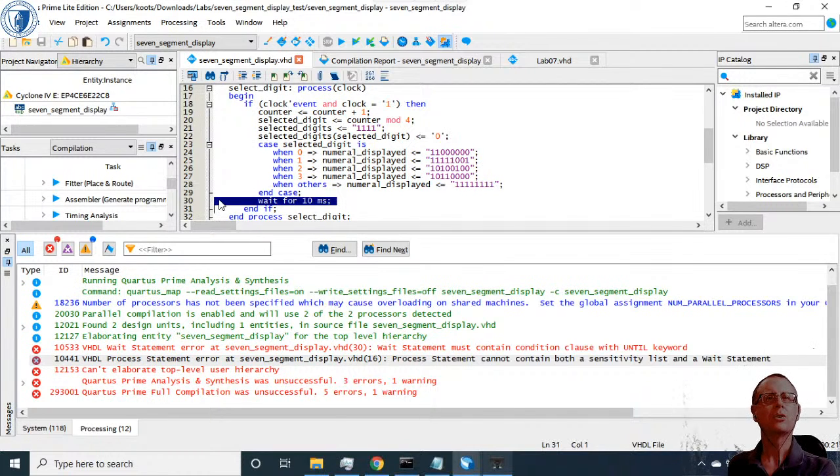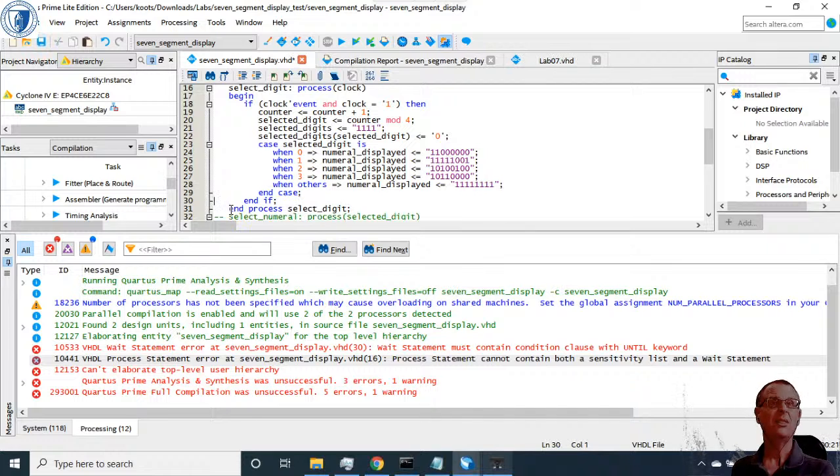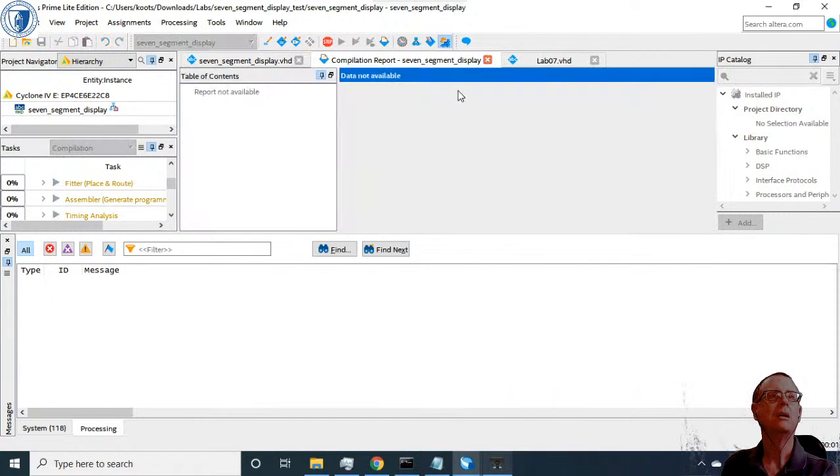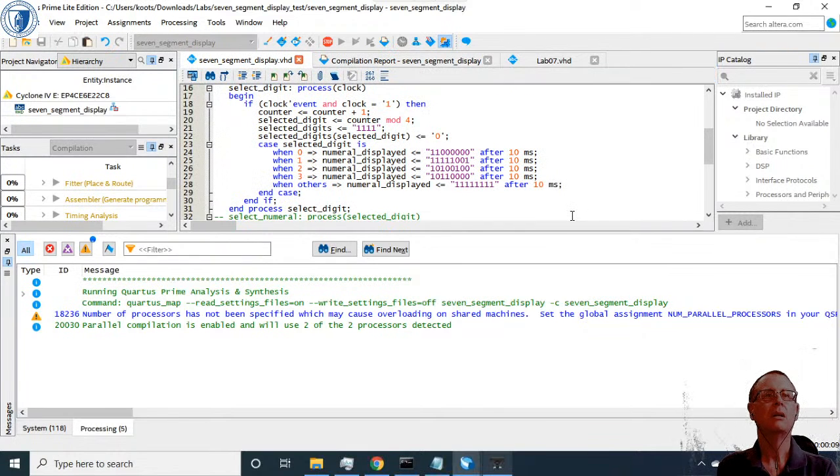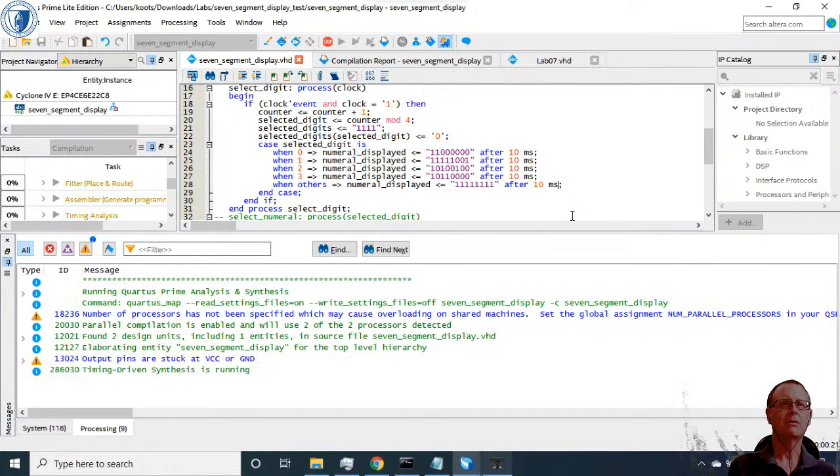I do want to trigger it on the clock. So instead of doing that, let's just do a delayed assignment. See if that helps. Don't know whether I'm using the right syntax there, but otherwise I'd have to take the clock out of the process sensitivity list and then I'm not sure I'd be able to actually trigger on the rising edge.